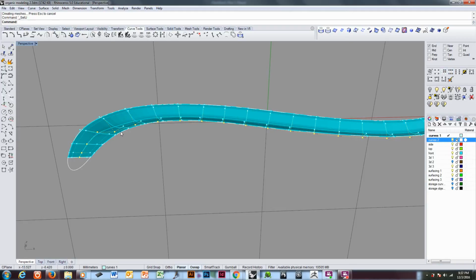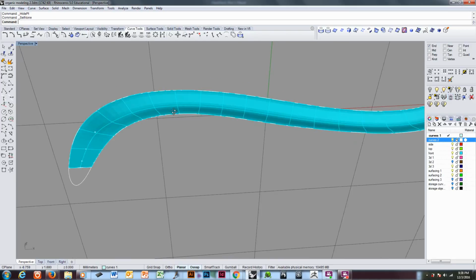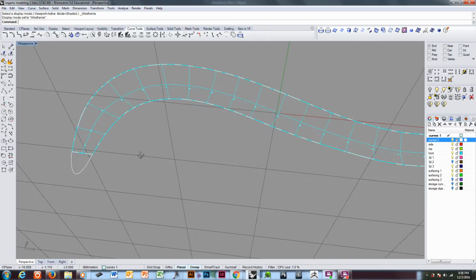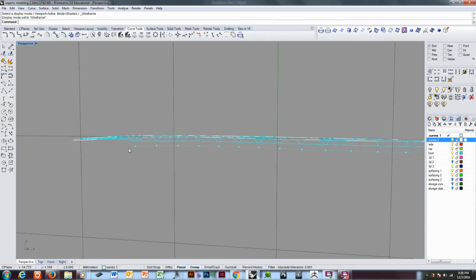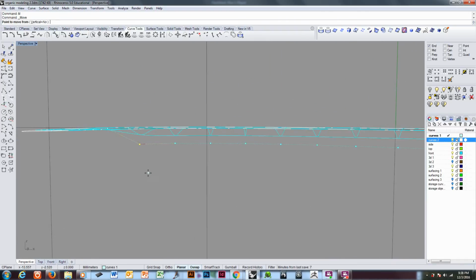I'm going to select the full row of points again, and I'm going to come down here to the visibility. This is the button I use all the time. I have this whole panel here just for that button. It inverts selection and hides the control points. So it means it's going to hide everything but that row. I'm going to go into wireframe because it will allow me to see the points better. And then I can do a more gradual, more controlled fall off here.